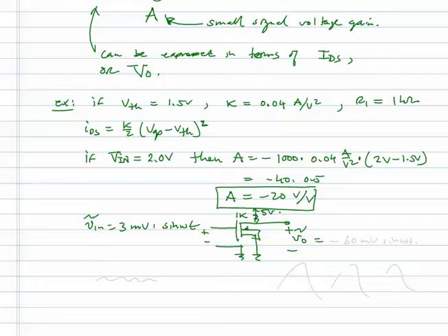So you have amplification. You put in something small, and we get something 20 times larger. The key to figuring out the amplification is simply going back to that DC transfer characteristic, and in that middle transition region, figuring out the slope at the operating point of your amplifier.